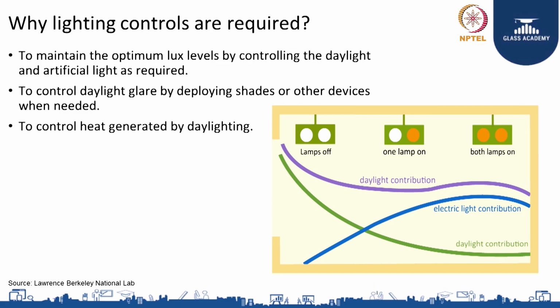So how are we basically achieving the control of the artificial light? We know that the daylight, when it enters from the window, it doesn't enter and reach all the spaces in the building. More daylight will be found near the window and less when we go deeper into the building. So this is not a uniform distribution. Therefore, the interior lights also should have non-uniform control. It should not happen that all the lights are dimmed equally.